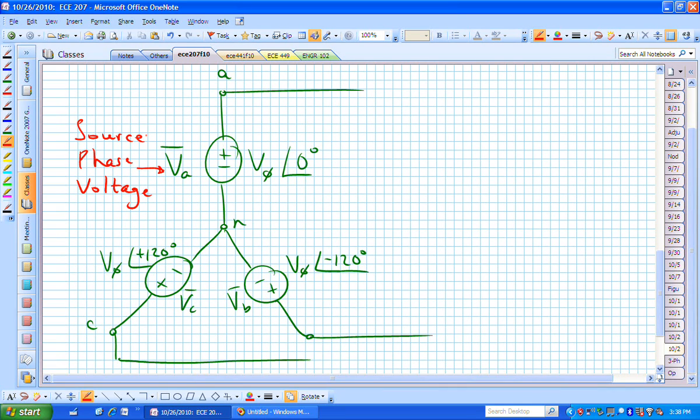What we might be interested in is measuring with our, let's say, multimeter this voltage V sub AB between the A line and the B line. The phase is from the line to neutral. The line in this configuration, in this interconnected structure, is between line to line. Question?